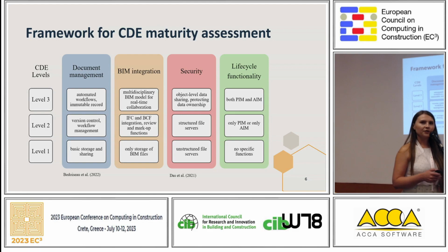The other very important aspect is the integration of BIM with the CDE. The basic solution just provides the ability to store the BIM data, but in level 2, it should also provide integration with IFC and BCF formats and direct revision, viewing, and markups of the BIM models. But ideally, in the most advanced level of CDE, it should provide multidisciplinary and real-time collaboration on BIM models.